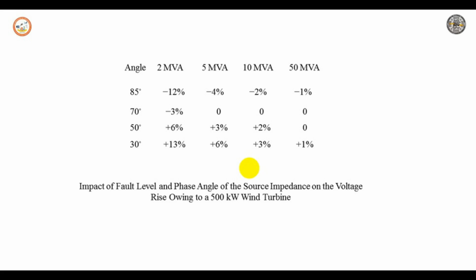The regulators will make a wrong detection when there is a reverse power flow in the power system. Tap changers equipped with line drop compensation are also less prone to this overvoltage. The presence of a generator on one feeder will result in a voltage drop on the other feeder.